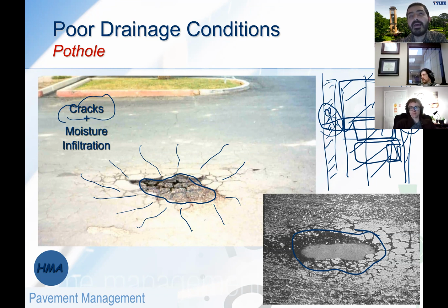Typically for any pavement structure, we try to design hot mix asphalt with 7% air voids. Those locations may end up with 9 or 10%, which means there are lots of air voids inside the structure, which is a very welcoming environment for water to get in and infiltrate. And if there is any spot or batch that is not compacted as much as it's supposed to be, that's going to end up being a future pothole.